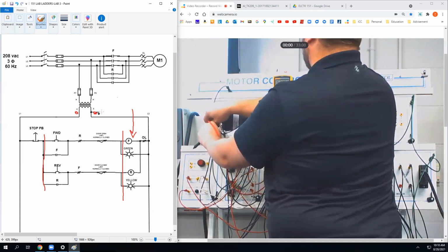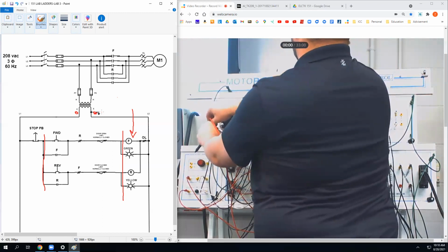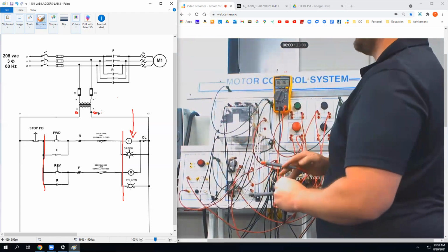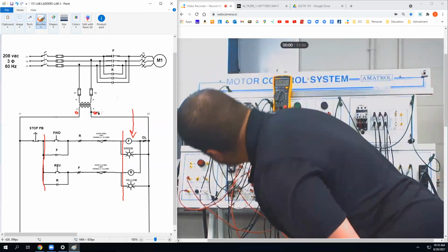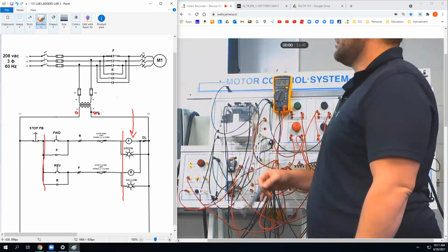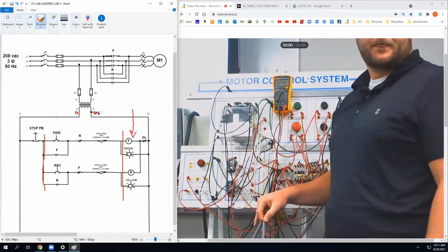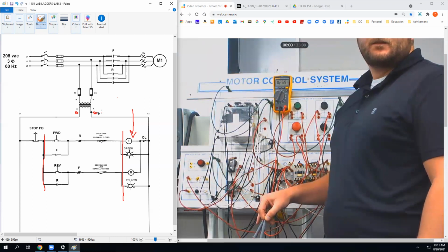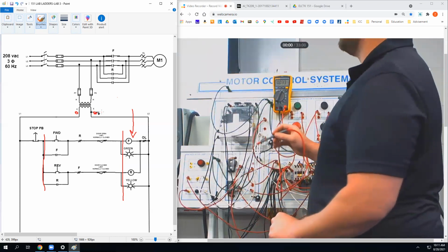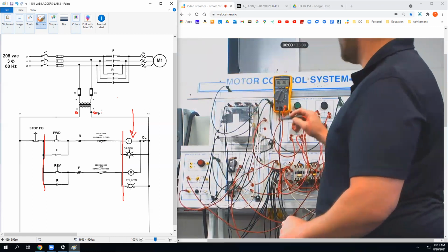No, I'm just confused why I'm getting a little jump in voltage. Okay, so nothing on the low side or the line side. So X1, or H1 and H2, have basically 0 volts going to them. So you look at the power circuit. Let's check the fuses first, right? Keep working your way back. So load side of the fuses.